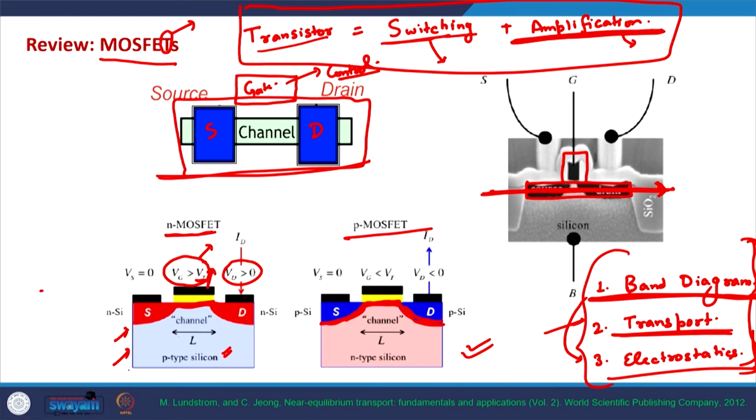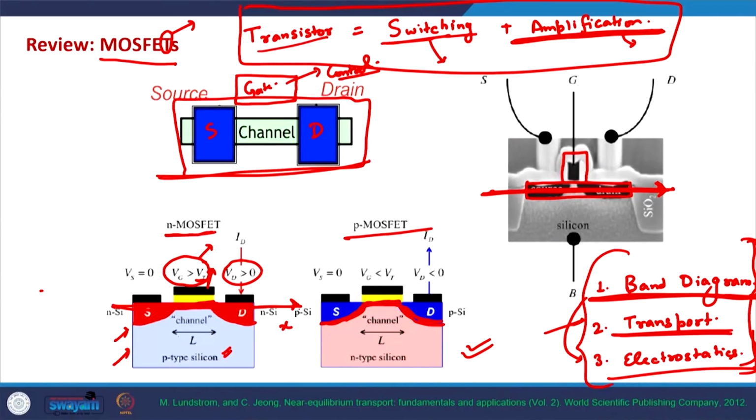So, in this direction, let's take the case of NMOS, and let's call this direction the x direction. We have an n-type material on one side, again n-type material on the other side, and in between we have a p-type material. So there are sort of two junctions in this direction that we will encounter if we traverse from source to the drain terminal.